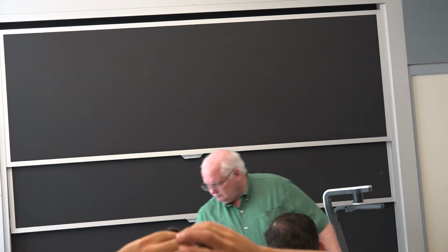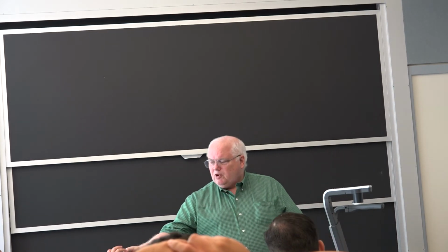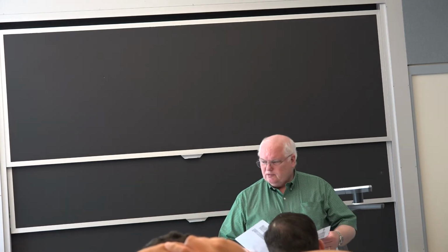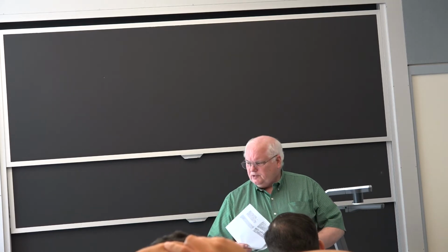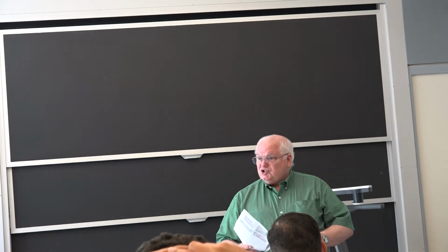But it turns out, fine composites, fancy composites, this is something you'll probably see on the videos a number of times. This is part of the X-33 space plane. The whole thing was a failure, and you'll get some of that in some of the lectures, but that's a Nomex, which is like Kevlar, honeycomb composite with carbon fiber reinforcement plies as the outside and inside sheath, and it's all adhesively bonded together. And it only costs $12,000 a pound. How about that? Cheap at half the price. Well, expensive at half the price.